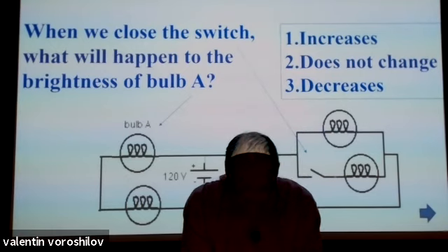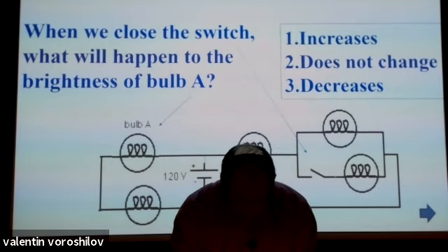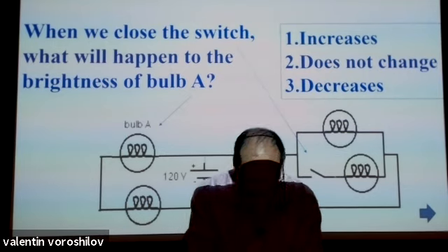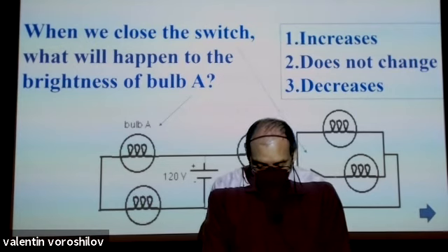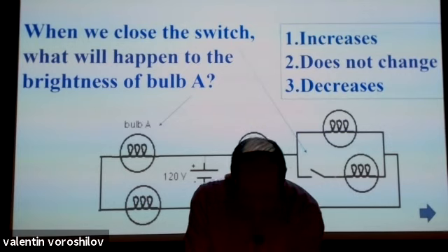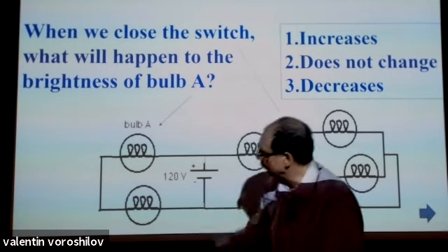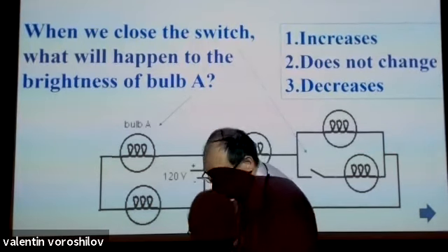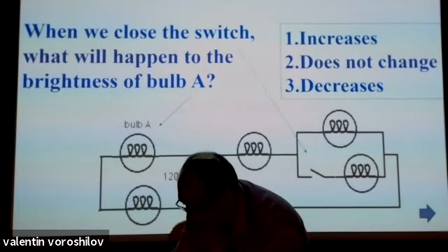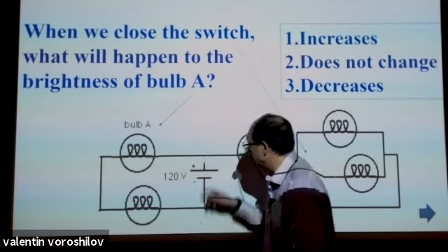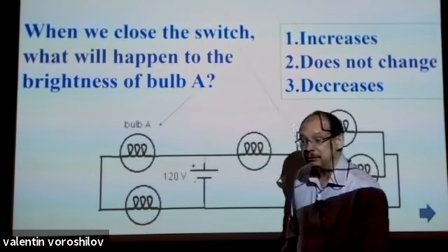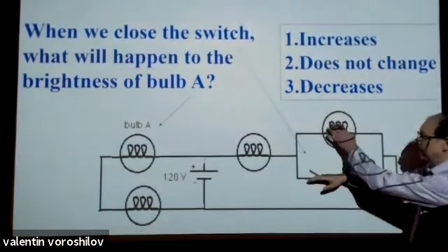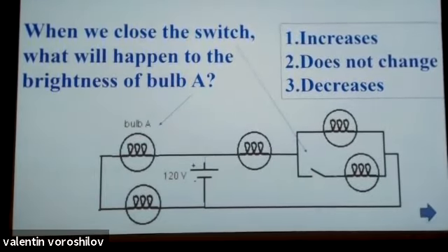It doesn't matter how I move elements and wires. It does not affect anything physically. It is only in our mind. So, an actual wire is always flexible. That means I can redraw any wire in any way. I can redraw any circuit in any way. What do I need to preserve? I need to preserve the connection. That's it. If these are in series, they must remain in series. If these will be in parallel, they must remain in parallel. That's it.